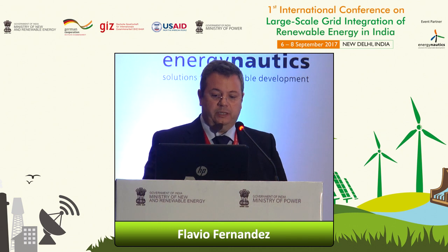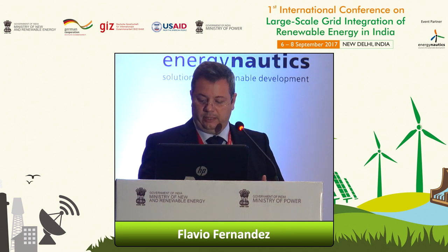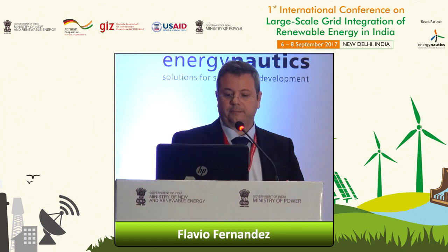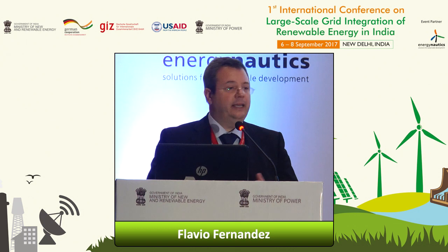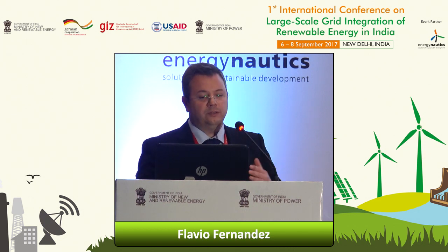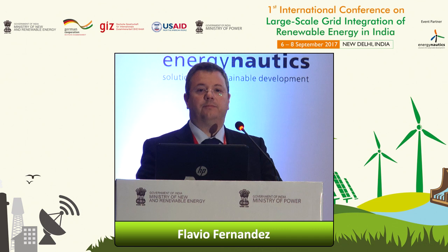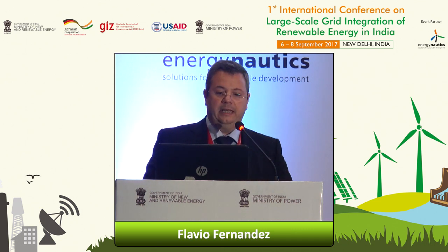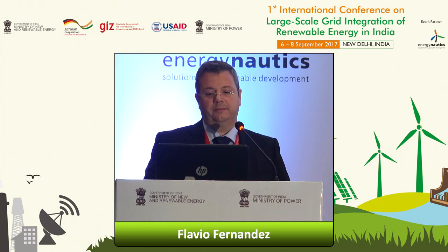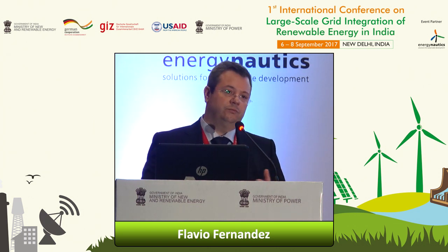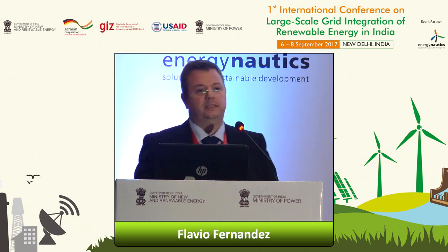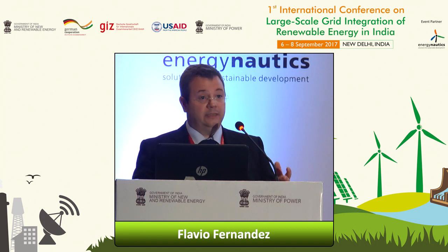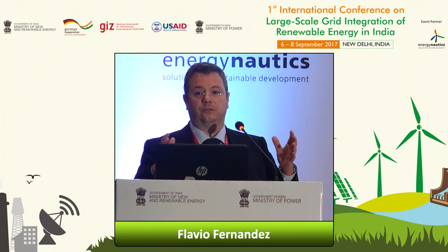And then we come to maybe the third and last category. Sorry, I skipped that: the so-called generic RMS type models. Again the characteristic is a fundamental frequency, RMS type, positive sequence representation. So far in the standards, you will only find positive sequence. And this is indeed an open source model. That means the standards, I put here two, the IEC and the WECC models in the US, document and say, well, this is how the different blocks should look.